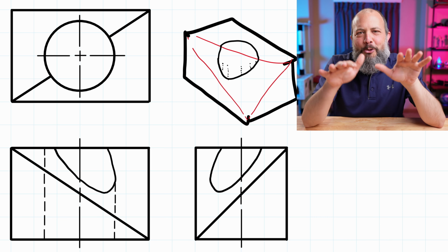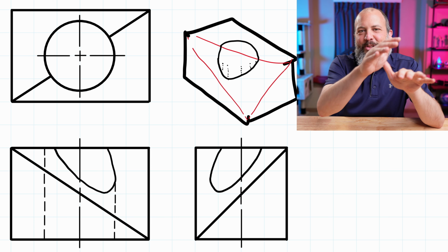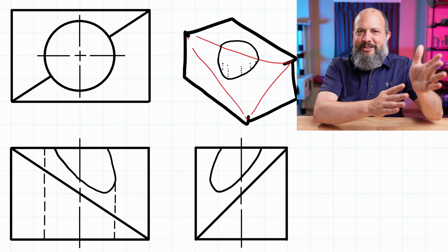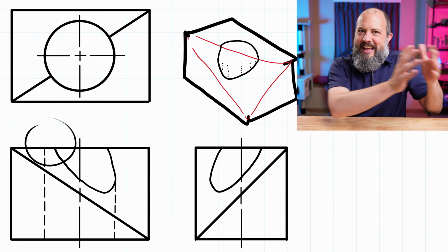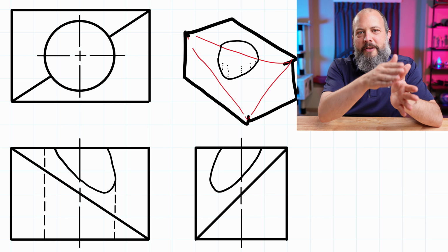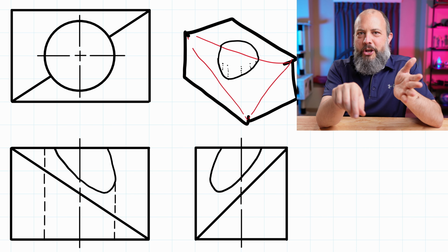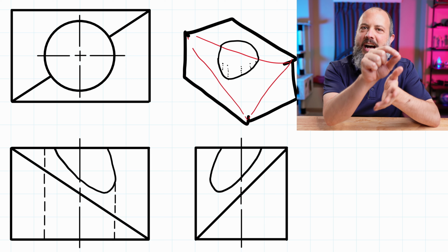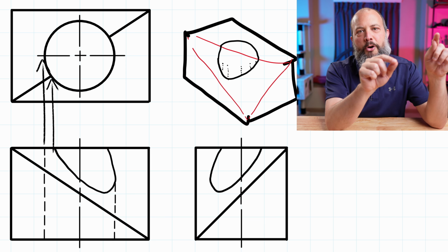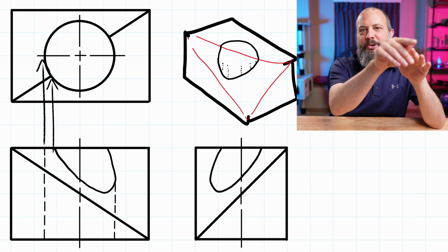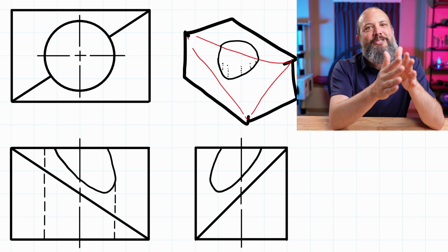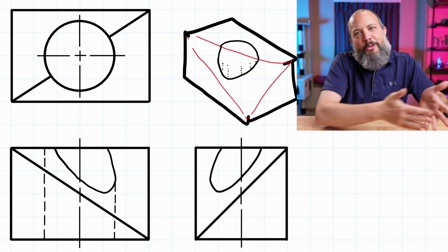And so this front view looks really strange. Like the circular hole is not circular. And on the left-hand side, the hidden line starts further to the left than the hole even is. But that's because when drawing the front view, where the curve intersects the top of my front view is not actually the leftmost part of the hole. It's where the oblique surface intersects the top view, which is close to the far left side, but not all the way to the left.